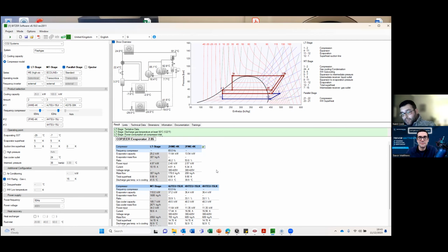Each one of those temperature brackets has a number of hours allocated to it per annum, and each one of those brackets will have a different COP, and that COP will depend on whether this parallel compressor is running or whether it's not running and it's gone back into flash gas bypass mode. And using a tool such as TEWI, you can then calculate what net annual average effect that parallel compression has on the efficiency of your system.